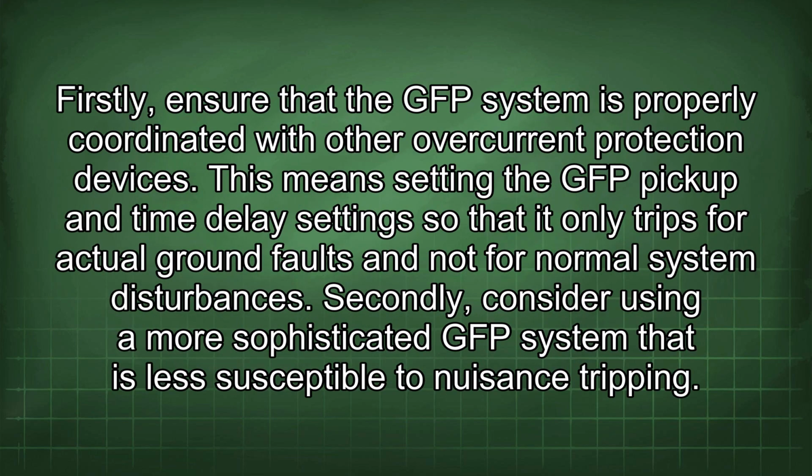Firstly, ensure that the GFP system is properly coordinated with other overcurrent protection devices. This means setting the GFP pickup and time delay settings so that it only trips for actual ground faults and not for normal system disturbances.